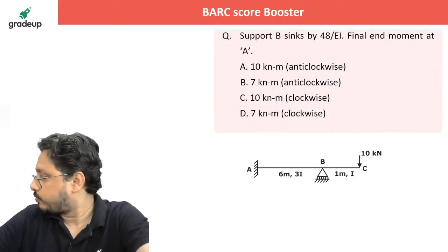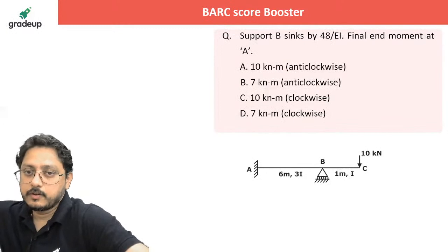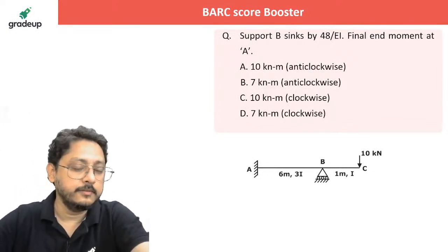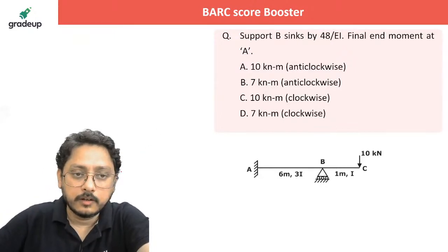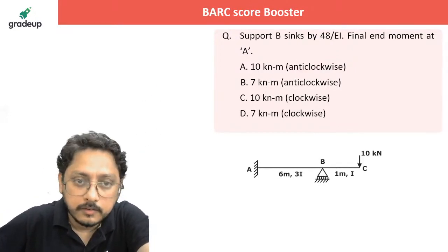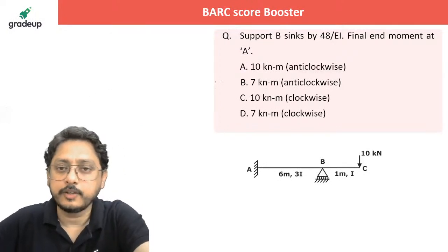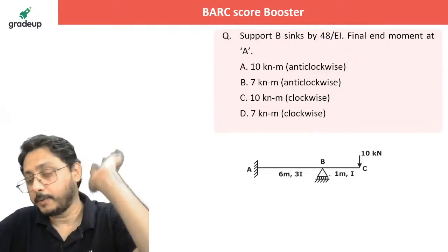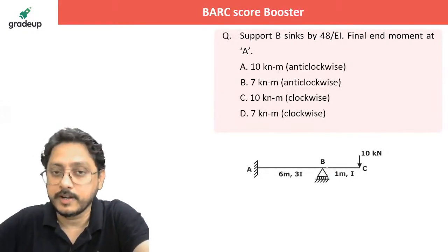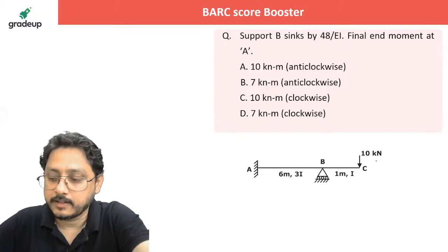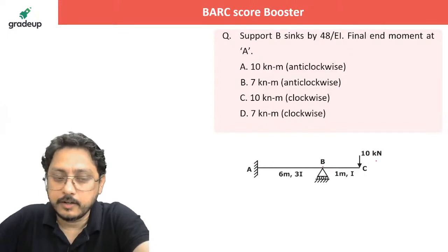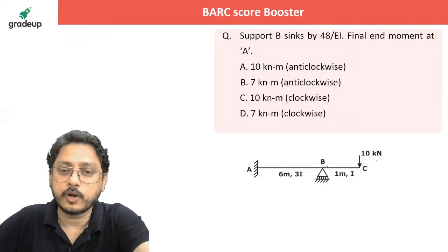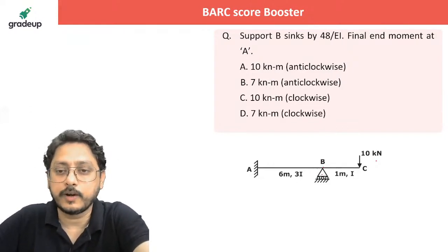Now it was the question which I gave it to you. Have you tried it? So simply if you apply the moment distribution method, but before application of the moment distribution, one should understand here, this 10 kilonewton is acting. So what will be the DF at this joint B, distribution factor at joint B? That is very simple, 1 at this side and 0 at that another side.